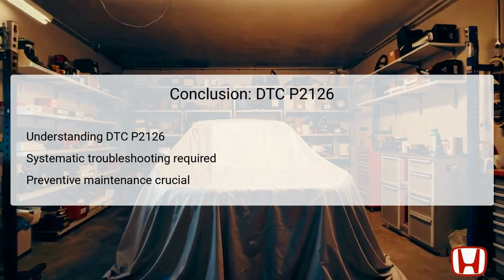Steps including checking continuity, repairing wiring issues, and substituting parts are essential for correctly diagnosing the error. Finally, preventive maintenance is crucial to ensure the vehicle operates without future interruptions related to throttle control. Addressing issues early enhances safety and performance, keeping the Honda Civic running smoothly.